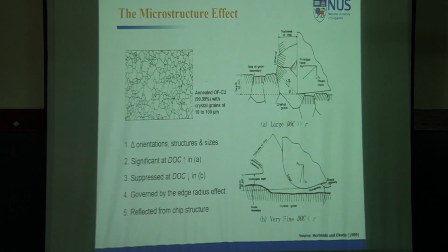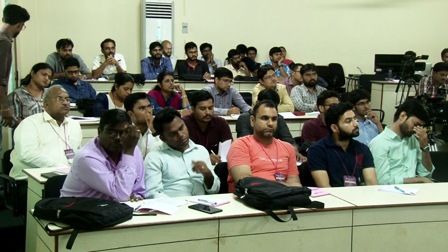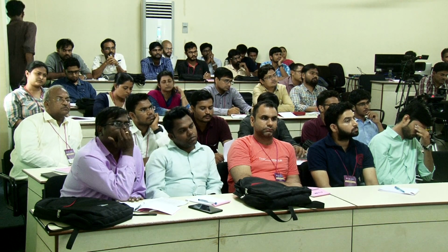I will come to that in the next presentation. Your compression is large enough that you do not allow the material to break along the boundary line. You suppress them. That's why extrusion takes place. Remember that. In extrusion, compressive stress is larger than your tensile stress. So this is the basic condition.